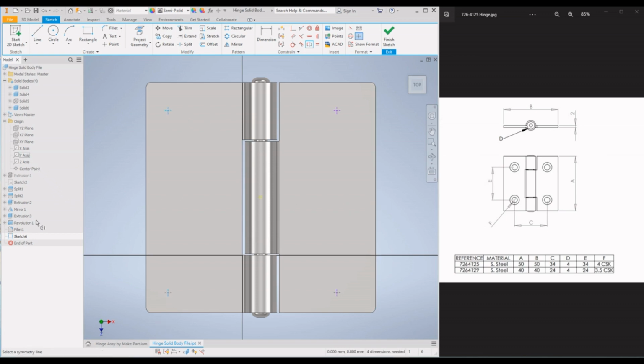Let's make it symmetric about the x-axis, click on the x-axis, and also click on the vertical axis, z-axis. Oops, you have to reactivate the command again. Click on this symmetric and click on this point and this point, click on the z-axis.